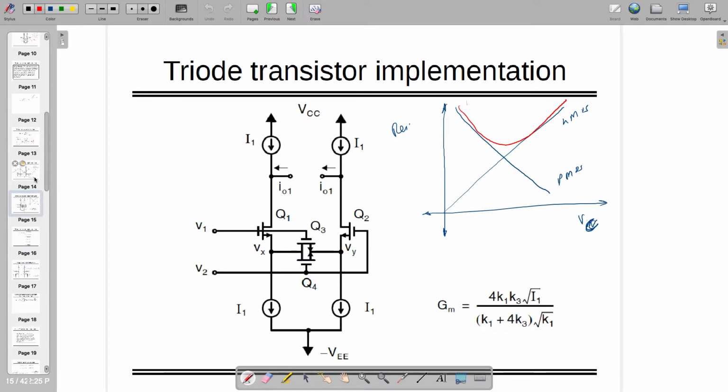The most important part here is when you are writing gm is equal to K times VGS minus VTH. But I am saying that the bigger gm, which is between this point and this point, and which is actually coming like this, where two transistors are in parallel, needs to be taken into account.